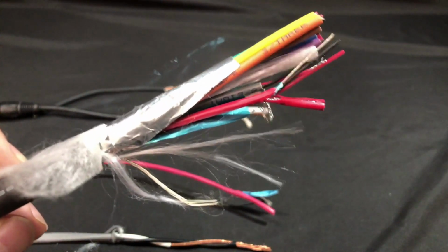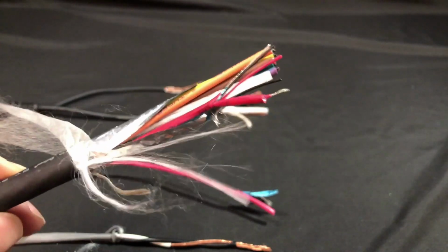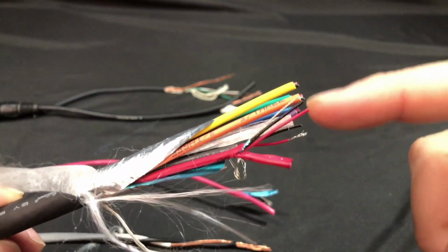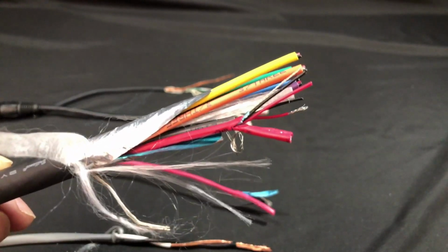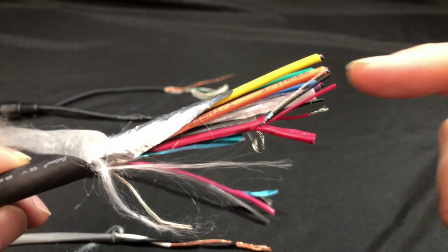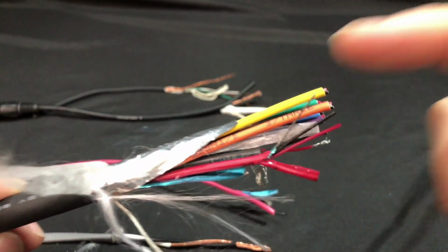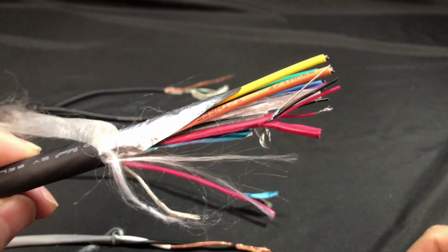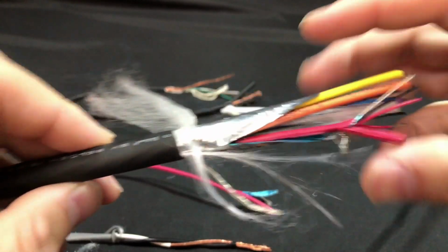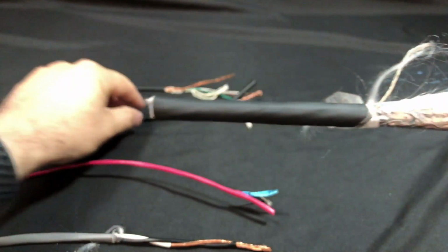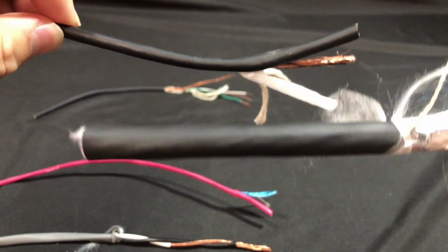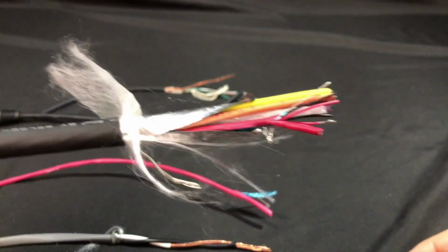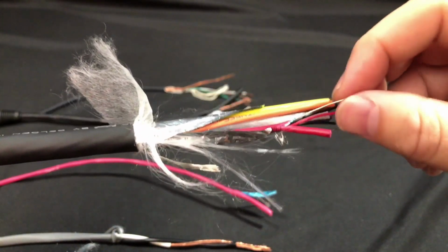And so this one's a little different because it's a snake. It has 8 microphone cables within it, and in each one there's 2 conductors. Well, 3 technically. One's not shielded with rubber. And the reason they decided not to go with a braid shield is because it would be too bulky, and the point of a snake is to reduce the amount of size. So if you can imagine 8 of these in here, it greatly reduces size, but they can't do braid shielding, so they sacrifice that with foil.